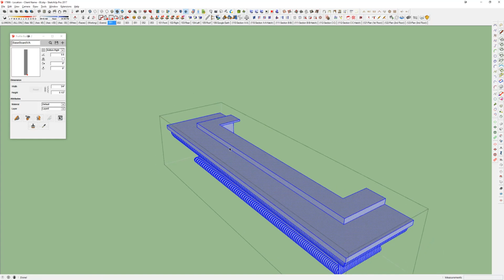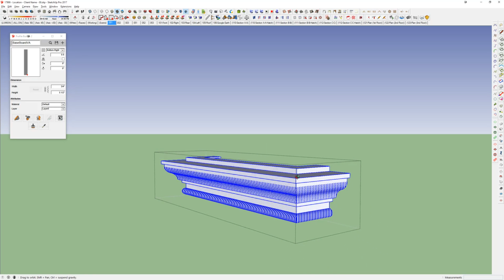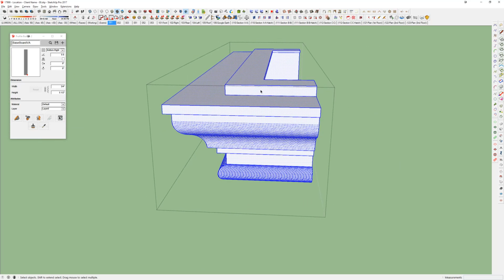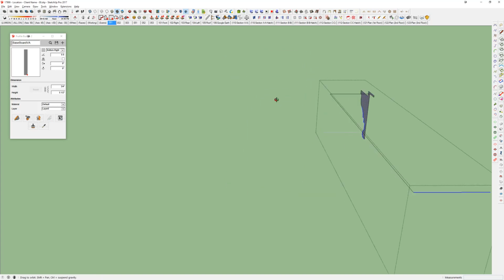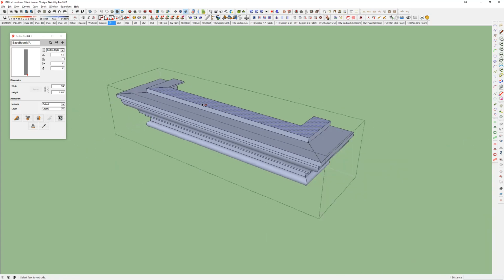I'm going to run my clean command, which we've talked about many times, and then Control R, or Shift R for me to change the faces. Yes, I'm sorry, I didn't specify what command I used. So, very basically, I have the outline. That's what these lines I was drawing were, the path in which I'm going to use the follow me command. And I have F set as my follow me. So I already have the path selected, then select my outline, and that gives me that.